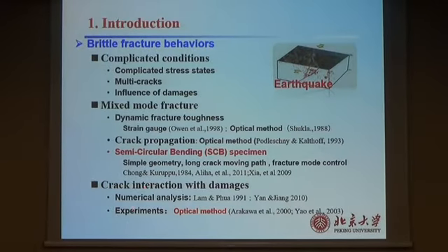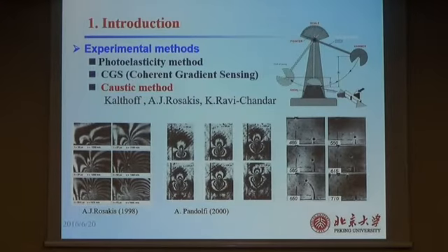And if we talk about crack interaction with damage, there is also some work about that. There are numerical analyses and independent work, but most of them are based on static loading conditions. If we consider the dynamic fracture process, the dynamic loading, it is so difficult to analyze. And if we use experiments to study the dynamic fracture problem, normally there is the impact toughness using the Charpy test. But with this you can only get the toughness of the material,